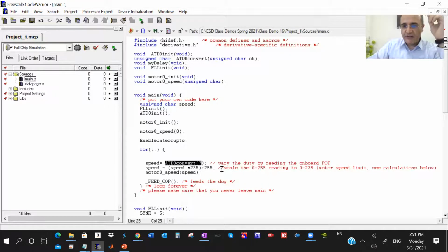Turning the potentiometer to the maximum left will stop the motor, or generate a PWM signal with pulse width 0, and the maximum right will be all 1, the maximum speed if I pass it to a motor.